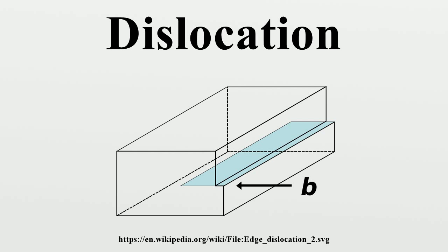Mathematically, dislocations are a type of topological defect, sometimes called a soliton. The mathematical theory explains why dislocations behave as stable particles. They can be moved around, but they maintain their identity as they move. Two dislocations of opposite orientation, when brought together, can cancel each other. But a single dislocation typically cannot disappear on its own.